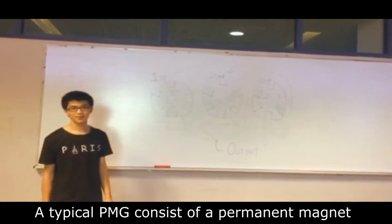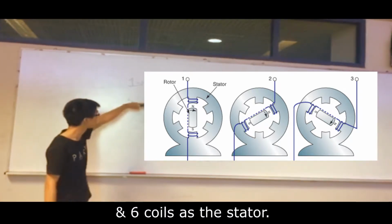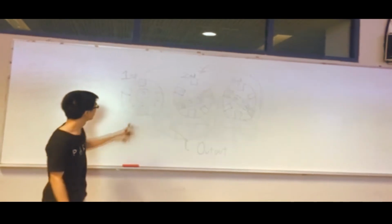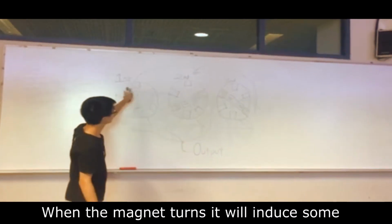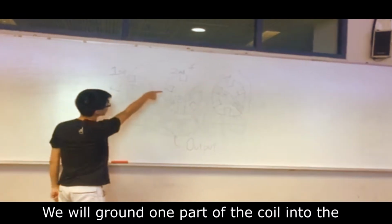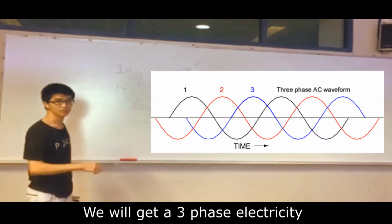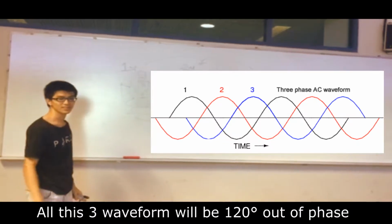A typical PMG consists of a permanent magnet at the center as the rotor and 6 coils as the stator. So there are a total of 6 coils. They are grouped into groups of 2, 1, 2 and 3. When the magnet turns, it will induce electricity in them. Then we ground one part of the coil into the neutral point, while the other part is used as the output. When we combine this together, we will get 3-phase electricity. All these 3 waveforms will be 120 degrees out of phase.